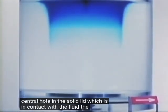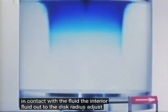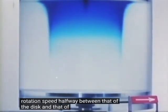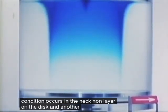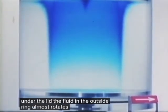The interior fluid, out to the disc radius, adjusts to a rotation speed halfway between that of the disk and that of the upper lid. The accommodation to the no-slip boundary condition occurs in an Ekman layer on the disk and another Ekman layer under the lid. The fluid in the outside ring almost rotates with the cylinder.